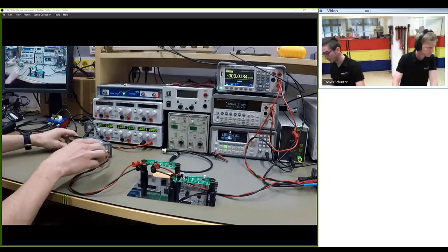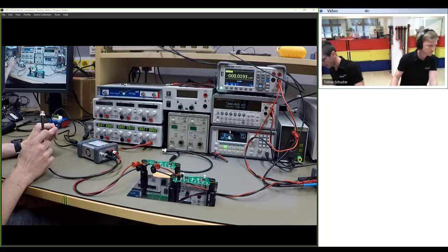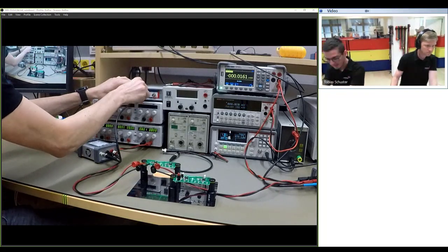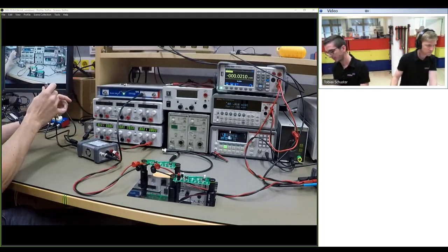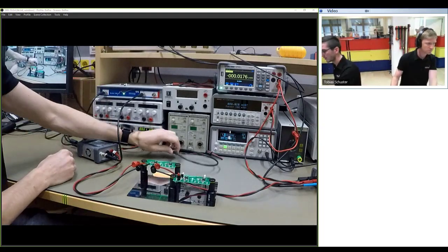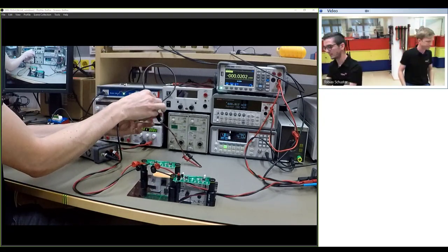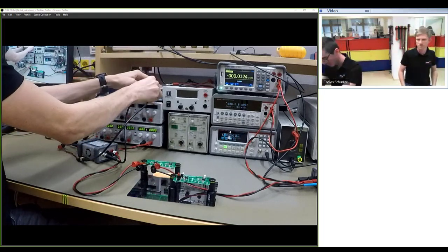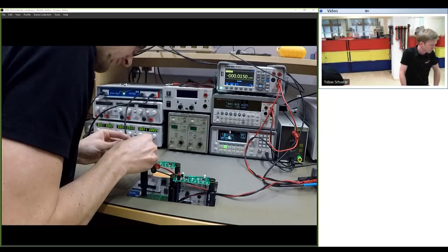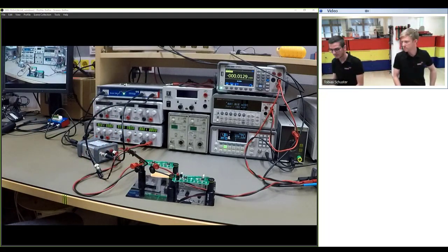So the line injector is already connected to the input. So I just have to connect the current monitor of the line injector to channel 1, the output of the Bode 100 to the oscillation input of the line injector, and last but not least I have to connect a voltage probe, which in our case is only a BNC cable, so a 1-to-1 probe BNC cable with 2 leads. So that is one to channel 2, and will be connected to the input of our device under test. So that's it. So Florian, I think you can start and open the Bode Analyzer Suite.